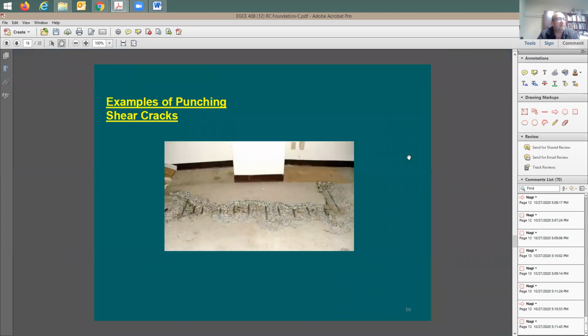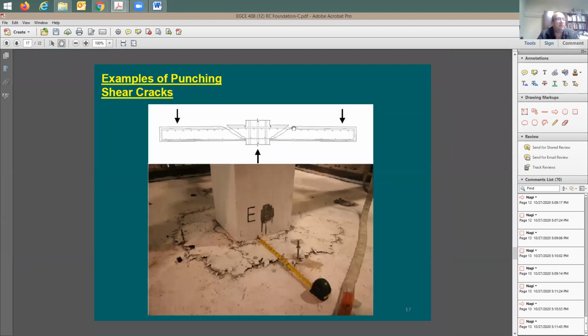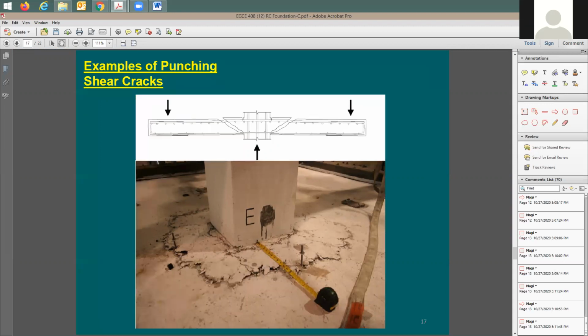Now, when this is cracked, we start to clean this area because the concrete is apart, right? It's pieces. So you need to chip it and clean it. All the loose concrete, you need to take it out. So how would you reinforce it from the bottom? Because you mentioned the FRP. So would you like steel members here? You need to provide steel members in both directions, like channels and things like this. And you need to design to take the force coming from the slab going to the column. You need to transfer it through these channels, and then you need to anchor it to the column. There are some calculations that you need to do.